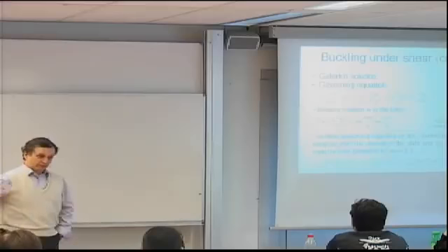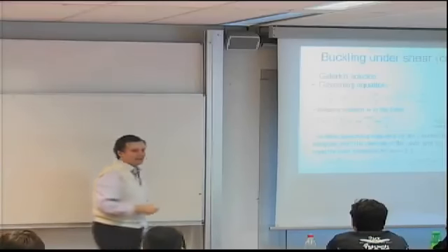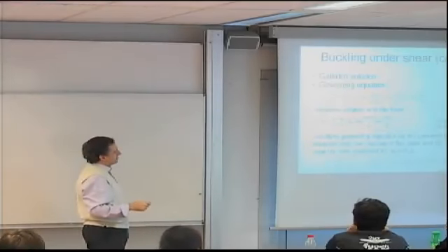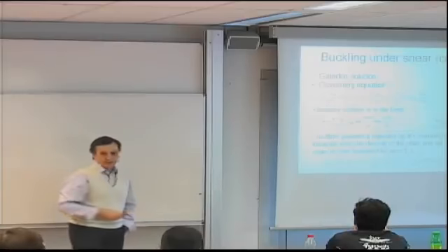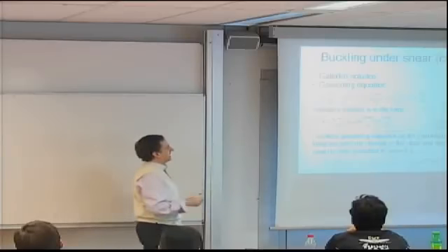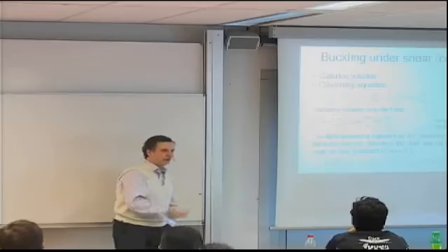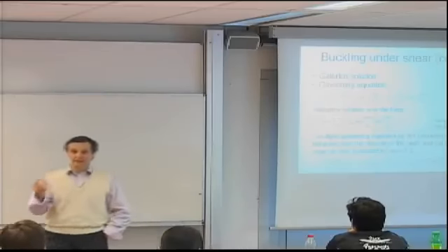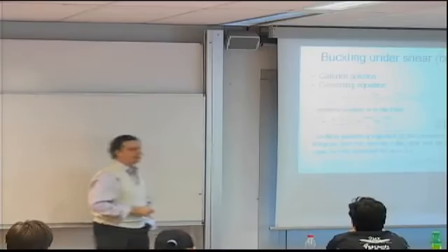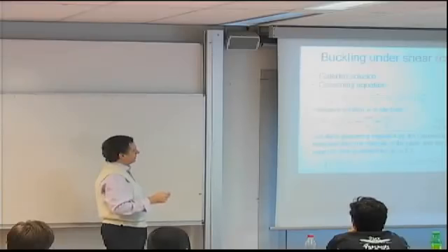Still, because we have gotten momentum from the way we were solving the problem before for the biaxial and compression, we insist, just because we don't know any better, on using a W that has the exact same form as before. Why am I doing this? Because, again, I know that if this satisfies my boundary conditions, it's a Fourier series, and therefore, by hook or by crook, it will still give me the right answer. It's just that I will get to it in a much more complicated way, as you are about to see. And the way we do this is what's called the Galerkin solution.